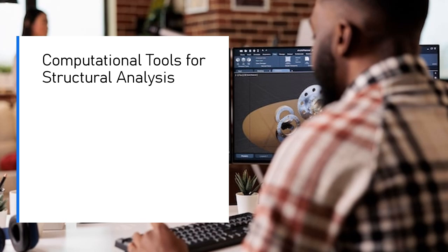Challenges. The Golden Gate Bridge was found to have vulnerabilities due to earthquake-induced forces and the increasing traffic load. The challenge was to retrofit the bridge's support structure to withstand modern seismic forces. Solution. The engineering team used SAP 2000 to model the bridge, perform dynamic seismic analysis, and simulate how the structure would respond to earthquake shaking. By incorporating dynamic effects, soil structure interaction, and foundation flexibility into the model, the team was able to design a retrofit plan that would increase the bridge's earthquake resistance.